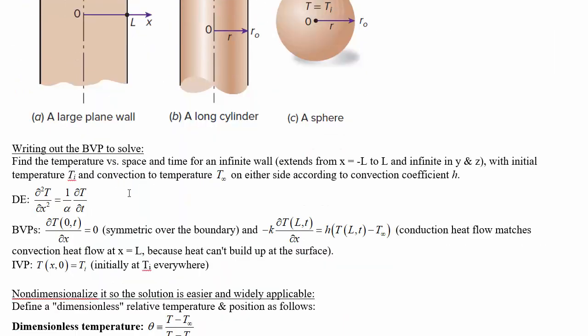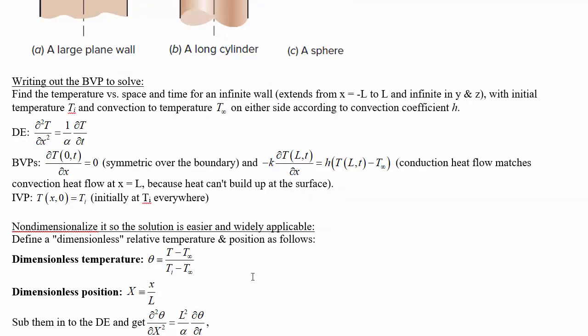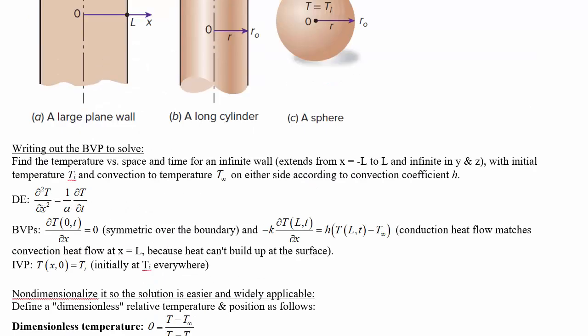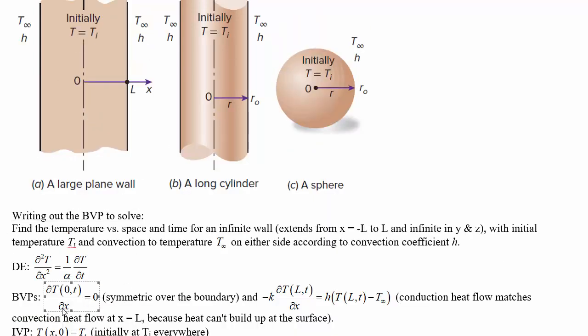Okay, so to solve this, the first thing we're going to do is to non-dimensionalize the differential equation. Prior to that, let's just re-examine what we've got, the differential equation that we mentioned earlier. The boundary conditions of this would be, first of all, symmetric temperature across the center.